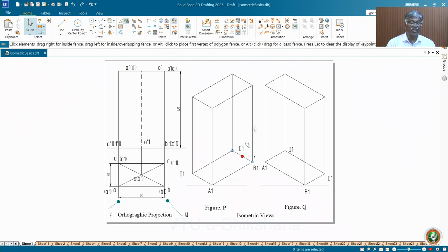Now draw vertical lines. All vertical lines remains as vertical. All horizontal lines are parallel to the ground or 30-degree lines. Only in case of square and solid, that is again condition is either parallel to or perpendicular to VP. That is possible only in case of square and rectangle. In case of pentagon, hexagon and all, we have many sides and they are inclined to their adjacents itself.